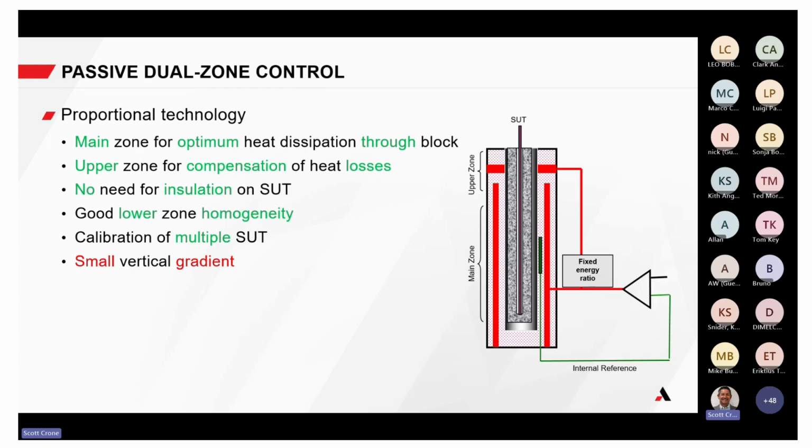And because of that loading question that you just asked, this will allow us to take care of multiple sensors, because as you add more sensors, that curve shifts even more and more away from true because of the loading effect. You've got more things trying to reach an equilibrium in the well. So this allowed us to calibrate multiple sensors under test, and it gave us a smaller vertical gradient. And it's great technology, but there's better.